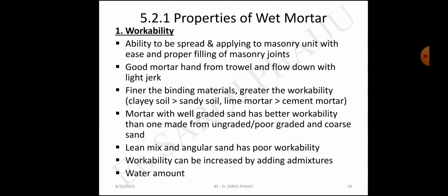Lime mortar is greater than cement mortar. Mortar with well-graded sand has better workability than one made from ungraded or poorly graded and coarse sand. Lean mix and angular sand has poor workability. Workability can be increased by adding admixtures.